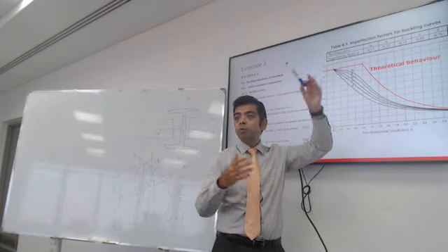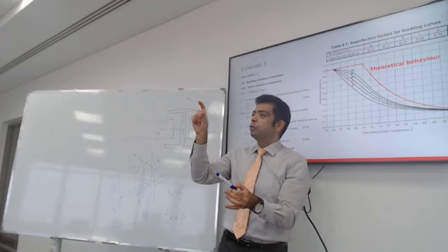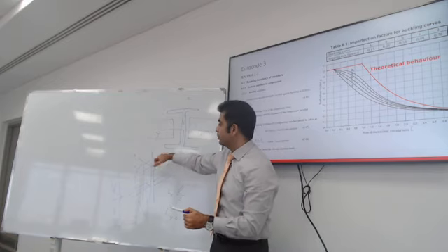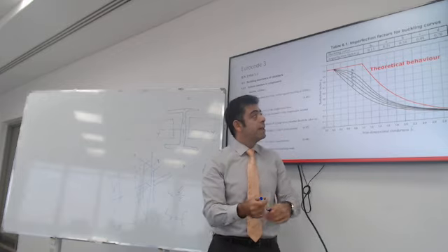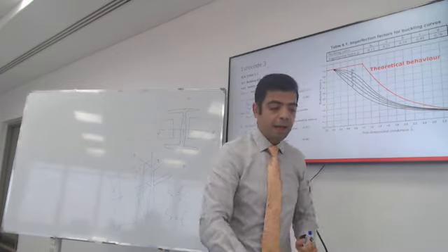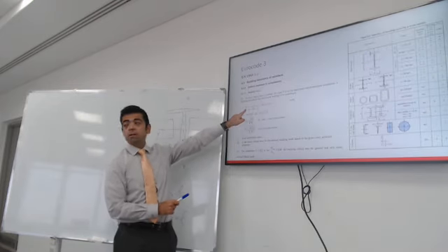So depending on the cross section, you go to the section you chose, figure out the direction you're calculating, what the buckling curve is, and then you go back and get the imperfection factor of it. And from there, you have all you need to calculate the reduction factor.